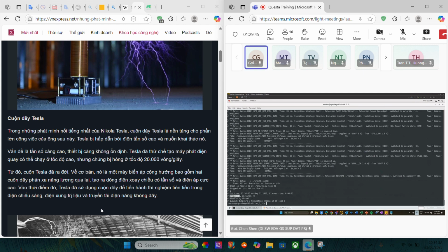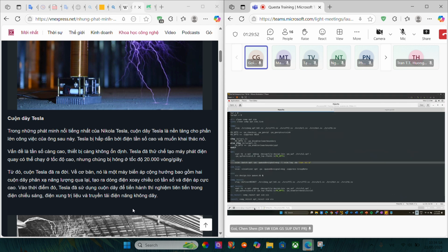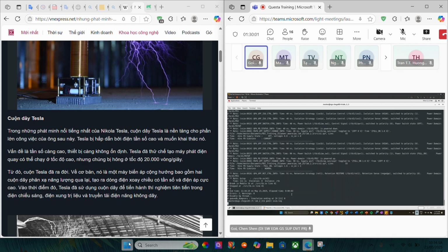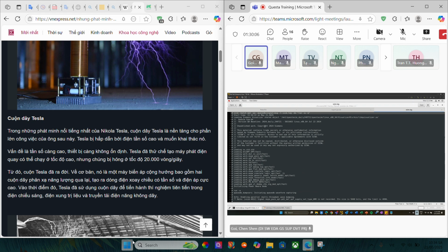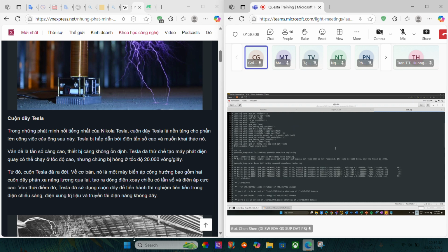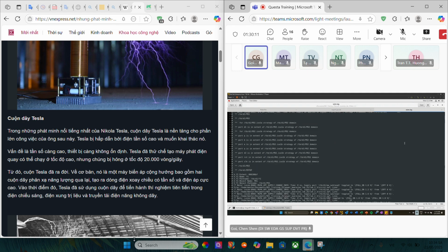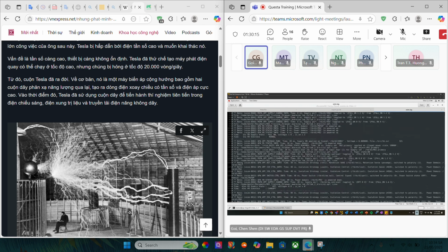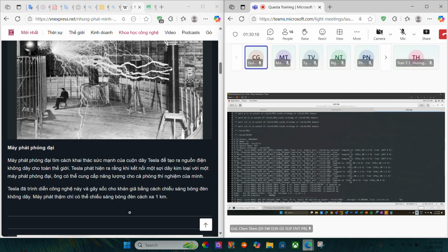Okay, after the run is finished, we can see the error is still there. Now let's bring up the log file from vsim.log. Okay, gedit. We should have it in our run directory. It's here, vsim.log. Usually how I navigate the log file is I go to the very bottom, and then I scroll upwards to see where the error is coming from. There are two errors, so there should be two errors written in the vsim log.